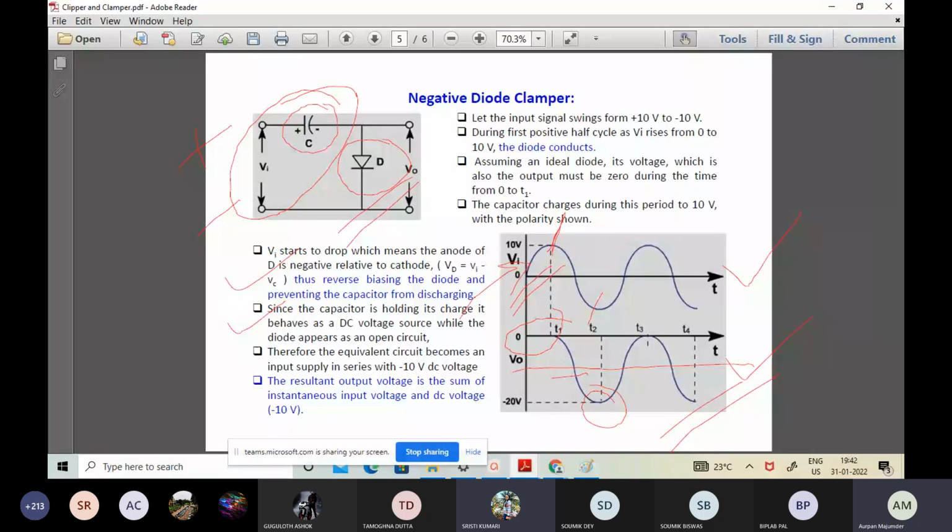Now, according to the circuit design, the output voltage is being observed across the diode. That is why we have a clamping operation here. We are not having the output voltage across the capacitor. We are having the output voltage across the diode. And hence we are justifying the corresponding clamping operation. When it is across the capacitor, then we can design a filter kind of issue. Here, the output voltage is across the diode. So it's a case of a clamper.